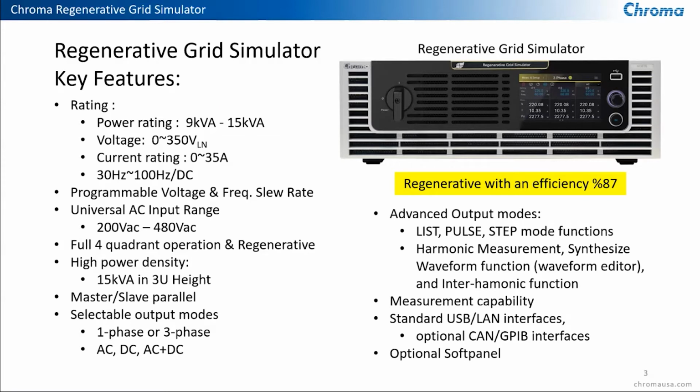It is a regenerative unit, and it's packaged in a 3U height design to minimize the space occupied in the system cabinet. You do have the capability of paralleling more than one unit to achieve a higher power, and it has a selectable one or three phase output, as well as a selectable AC, DC, and AC plus DC output.